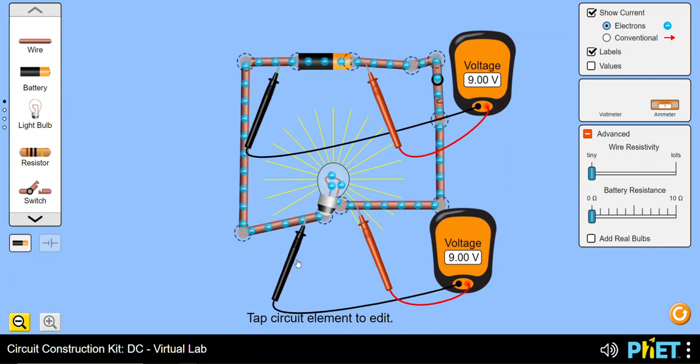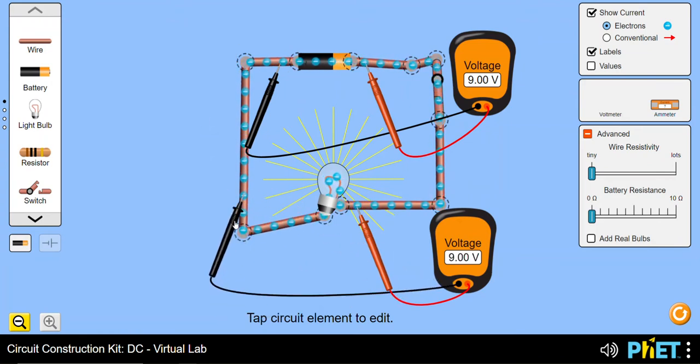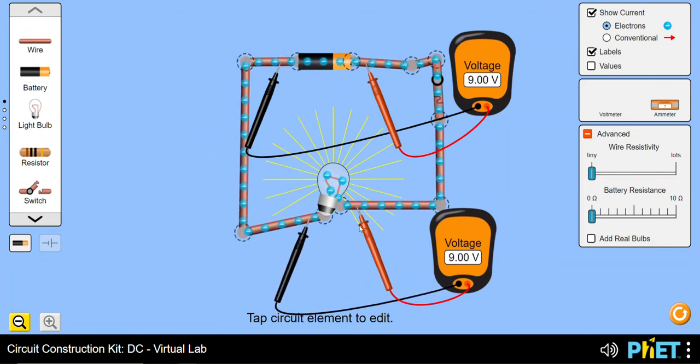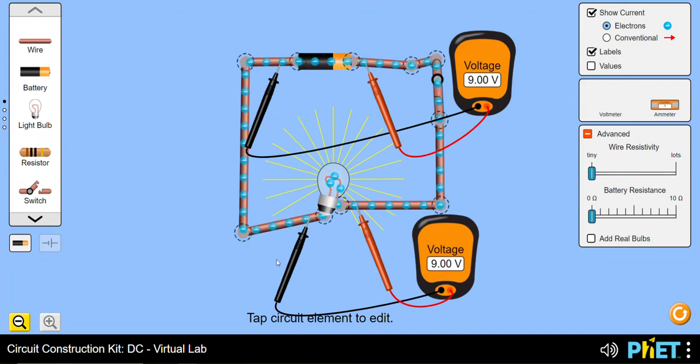The difference comes around this component, and it means that we can stick the voltmeter anywhere as long as we stick it on this side. We're always going to get 9 volts. So this difference is why we need to measure the voltage in 2 places. We need to know what is the difference in energy before and afterwards. We're measuring the difference in electrical potential energy between charges that were here and charges that are here.